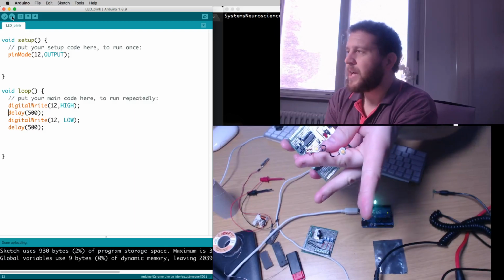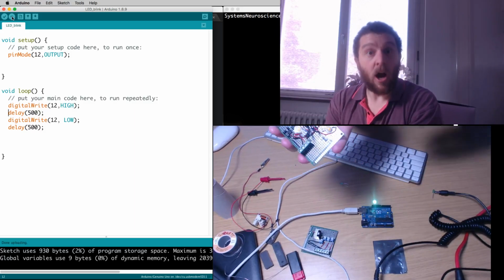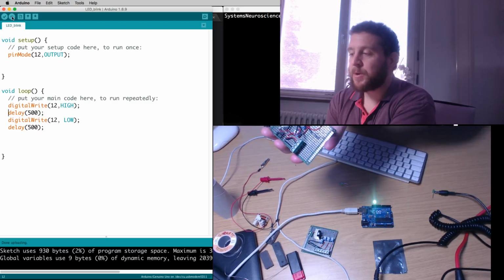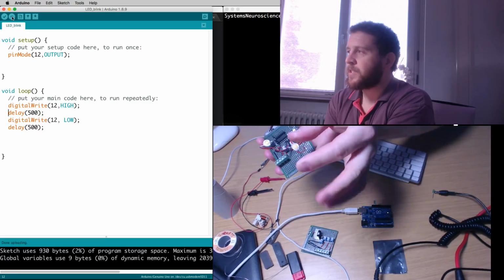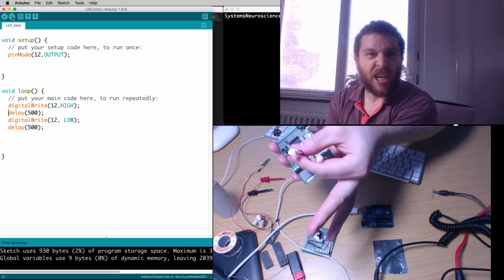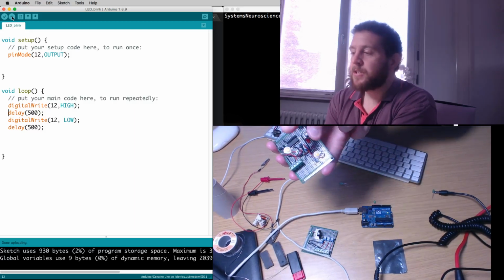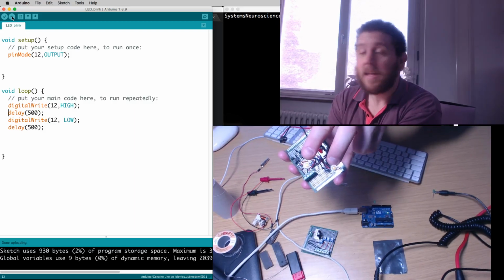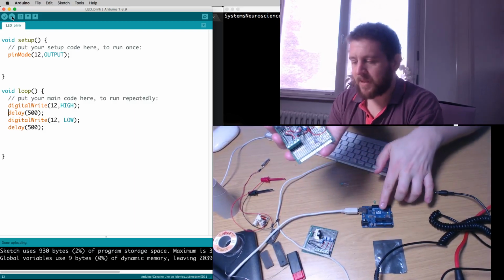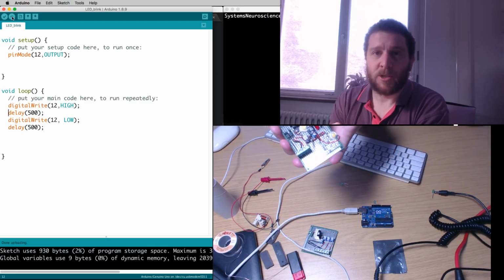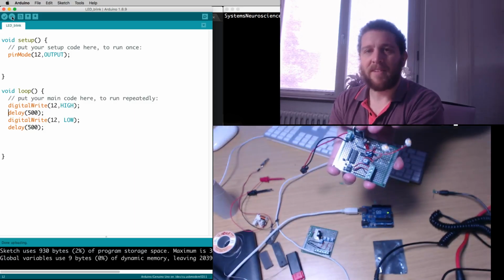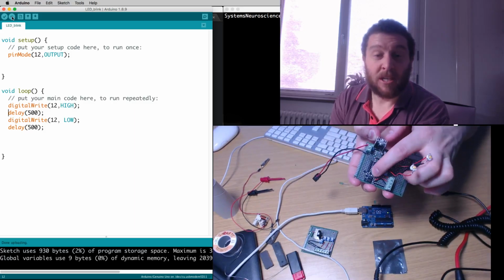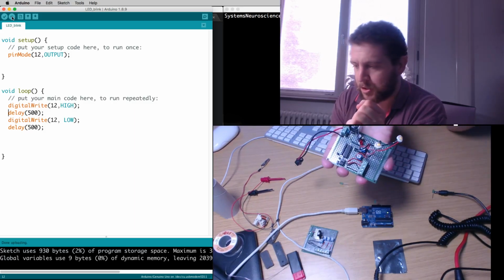But in our case, we have these ultra bright LED lights. I want to shine quite bright light into the arena, and that's going to require these really quite energy hungry LED lights. I probably want to turn on about 6 to 10 of them, which is going to be too much juice for what the Arduino can supply. So I'm having to use an external power supply and a switch. Essentially I'm using a transistor as a switch.